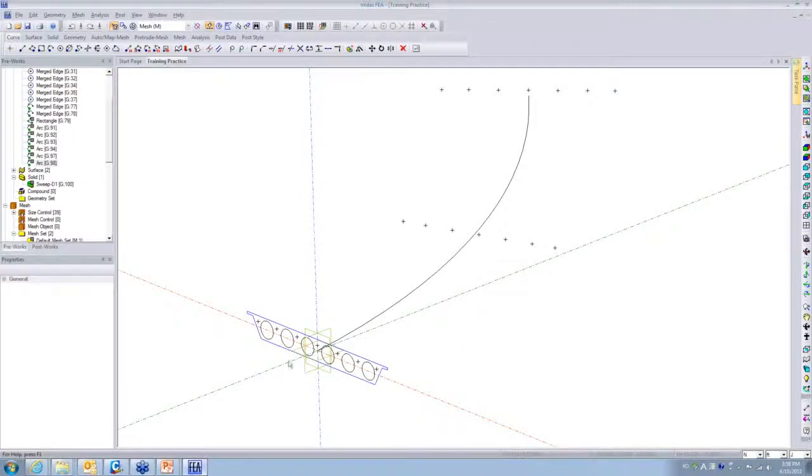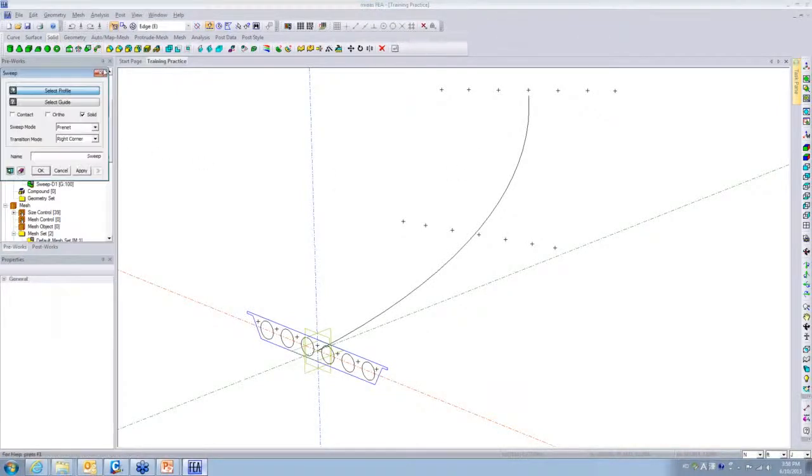So what we do, we can simply generate it. I can generate it for you. For example, I have this curved geometry, and I go to the solid and sweep it. Select the profile. You can select this and select the guide curve, which will be this guide curve.